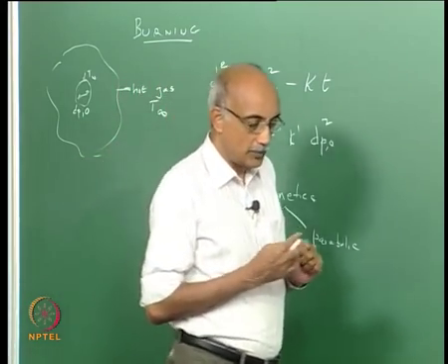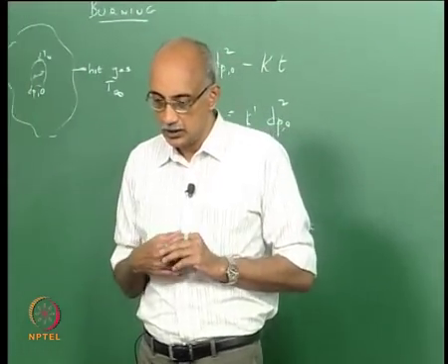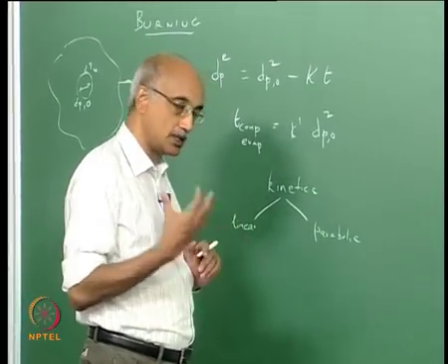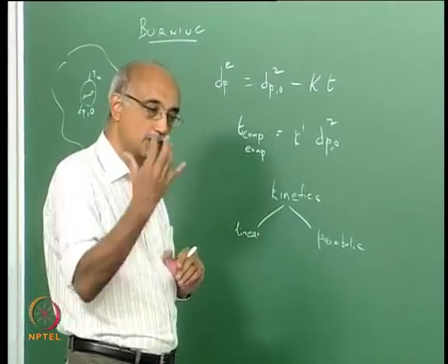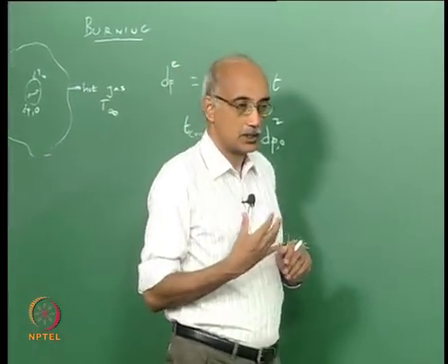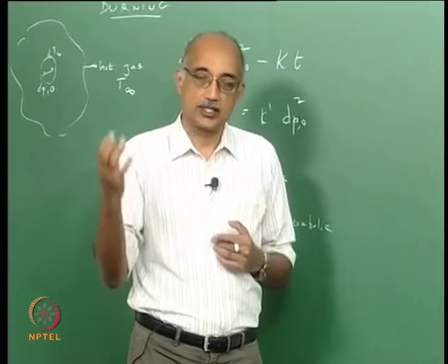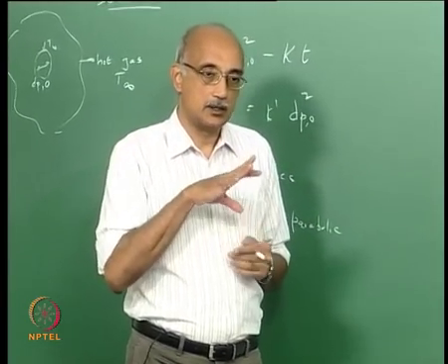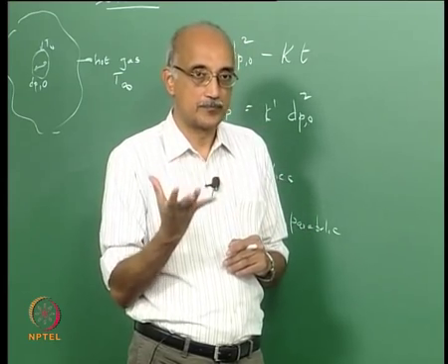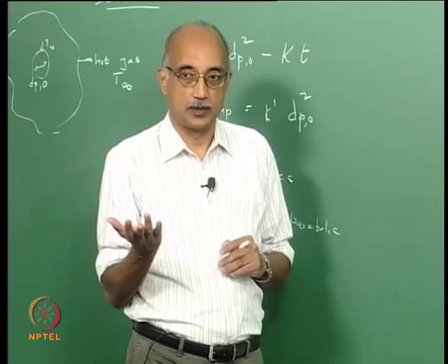But when you look at this problem of particle burning or droplet burning, it is essentially a process that is initiated by diffusion of energy from the hot gases. So, the energy transfer from the hot gas essentially provides the latent heat of vaporization that is required to convert the liquid droplet or the solid particle into its vapor form.